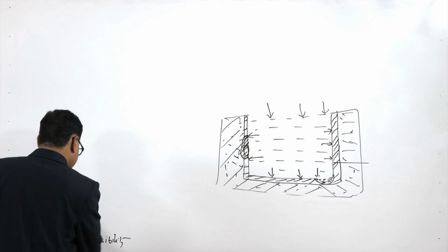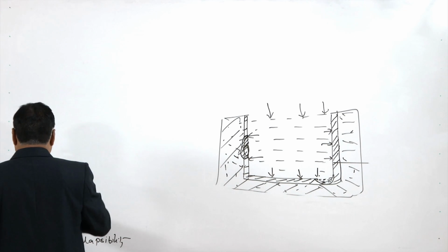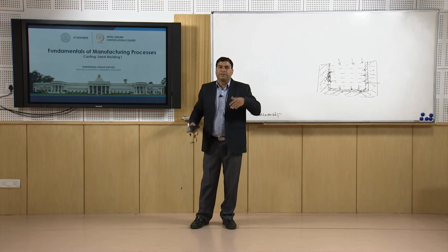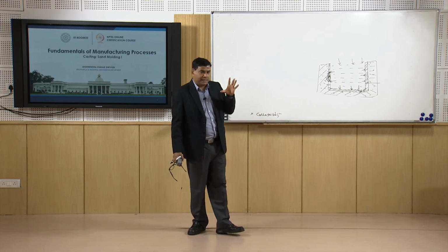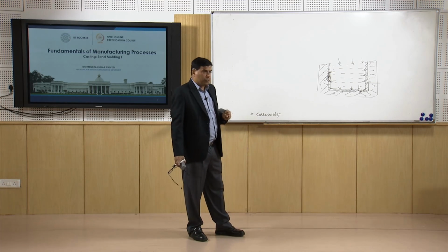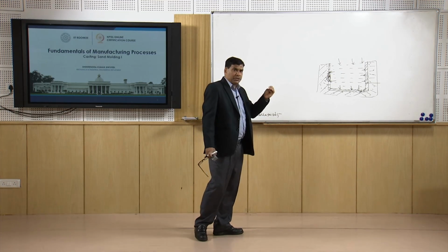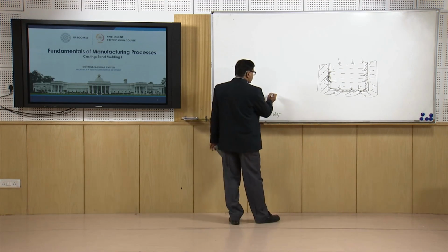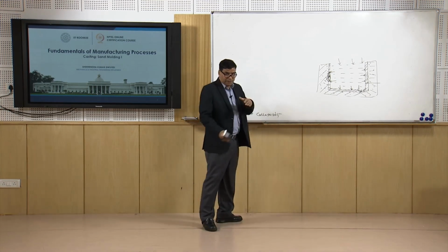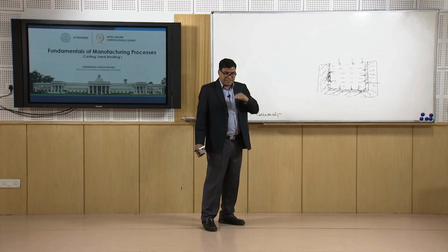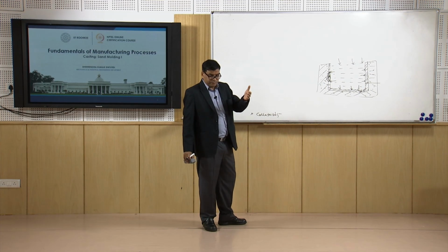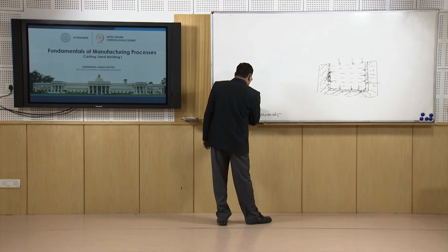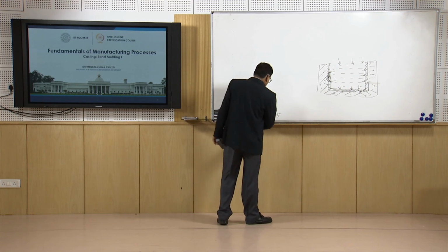So, it is necessary that the mold has the required refractoriness, and it depends upon a number of factors, like the type of clay selected, the size of the sand grains, and the temperature of the molten metal. We need to see that there is proper compatibility in terms of refractoriness between the molten metal being used for the casting and the refractoriness of the mold. Another important factor is collapsibility.